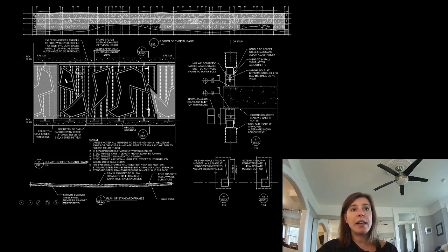So these were the details. These would be the cast-in panels and how tolerance would be built into it. So these HSS frames would slip in, shimmed tight, and then tack welded. So they could have the crane and a person inside get them in place. They'd wobble around a little bit, but they'd be stable until they shimmed it and tack welded in place. But that doesn't require your most expensive welder either. So it was taking all of the phases into consideration.